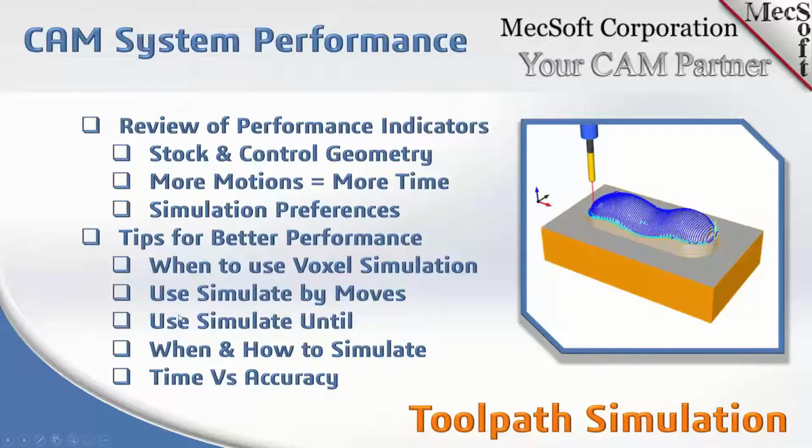And then we're also going to go over what it means to simulate by moves versus by distance, because in the default settings, one is faster than the other. And then simulate until, this is a little trick I mentioned. I'm going to show you how to bypass everything and cut right to the chase and get your simulation model displayed.